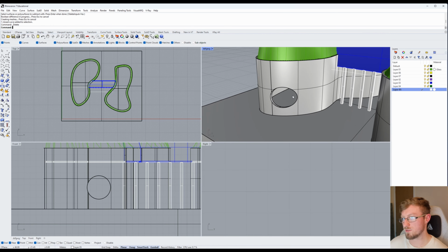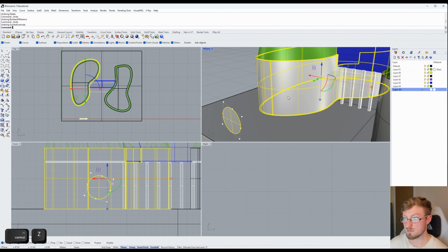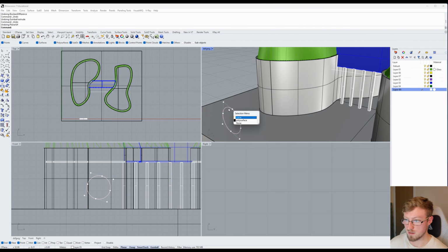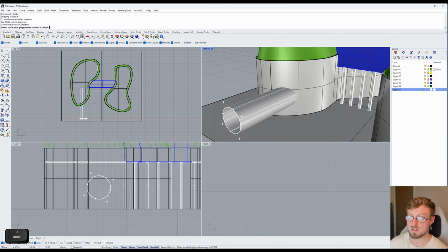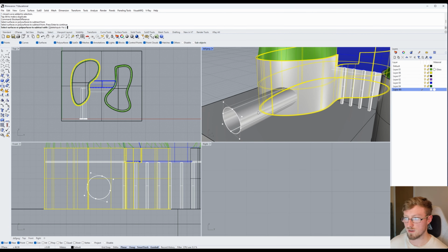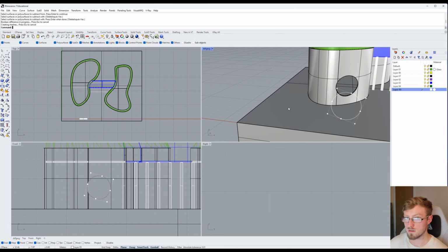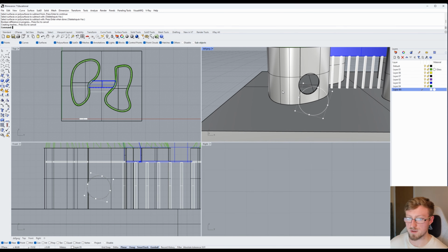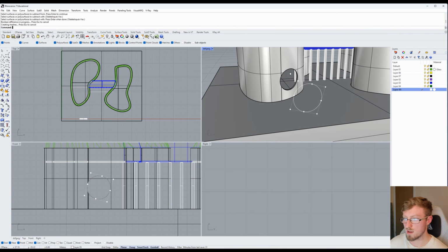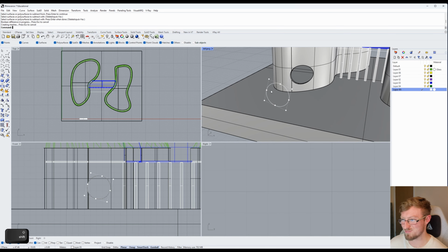If I tried that with just the curve, and then tried that, I'd get an error because, well, I don't know. I'll show you what I mean. If I now did this, drew that through, and then did Boolean, it has to be a solid basically with a solid. It also works, of course it does. I tried that many times on different things, and it's just not worked. Anyway, so with creating cuts into stuff, split, Boolean difference,